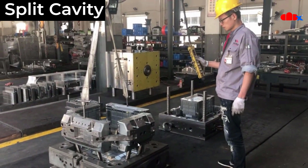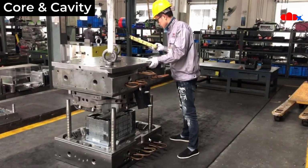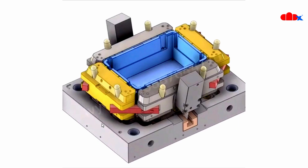Now this core and this cavity assembly will be used to manufacture this part. So both will be assembled together just like this. So here this assembly is the core assembly and this is the cavity assembly. So once this is assembled, there will be gap in between core and cavity, and that gap is your plastic part. So if you see the CAD model, it looks like this. So this is the cavity assembly and this is the plastic crate. Now the core will come from this direction. So in between core and cavity is this plastic part.